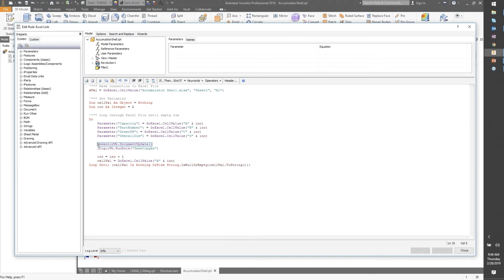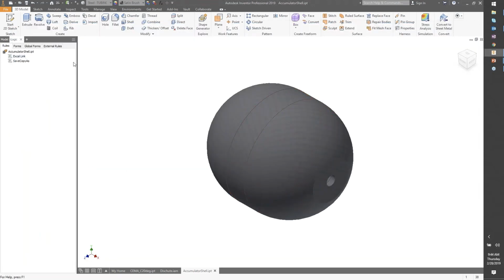I'm then going to update my file and save that file out as a unique file. Then it goes to the next row, and the next row, and the next row until it finds an empty row, essentially creating the different iterations that exist within my iPart table. So this is a very simple way of taking an iPart that could potentially create a performance issue